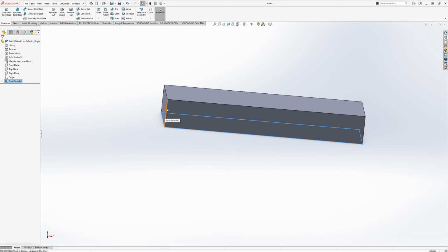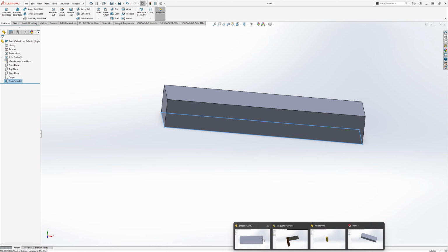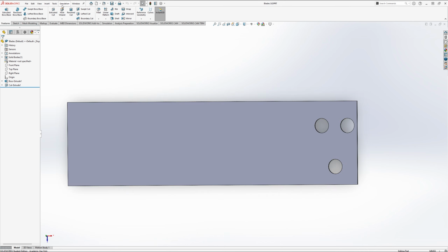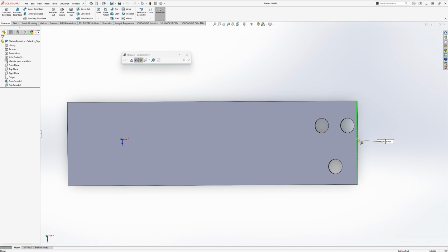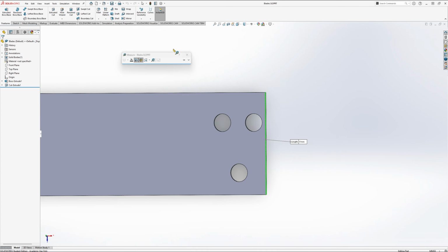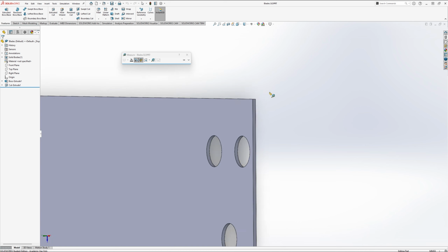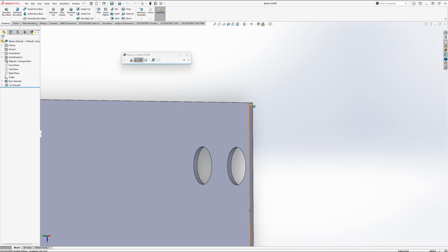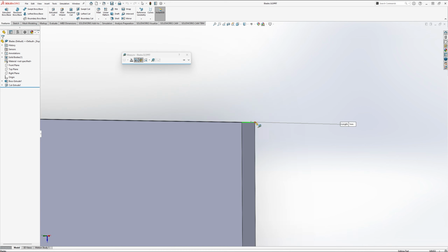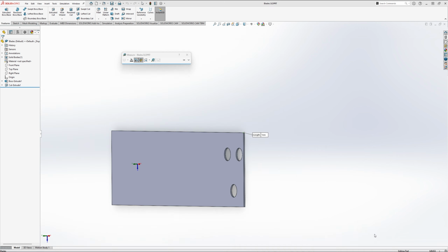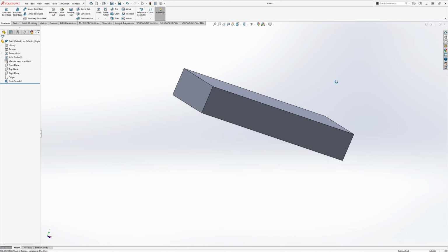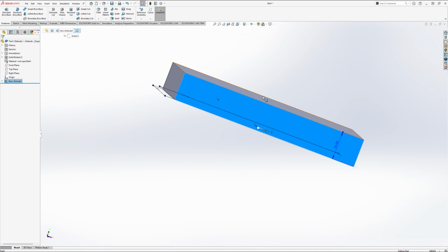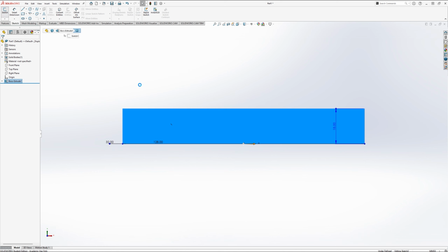Now what we need is a little slit here so we can insert the blade. So what was the width of the blade? Let's see. Go to tools, evaluate, measure, take that, which is 51, and the thickness was, let's just zoom in a bit further, 1 millimeter, so 51 by 1. Let's go back to part, click on the side face here, go to sketch, press sketch.